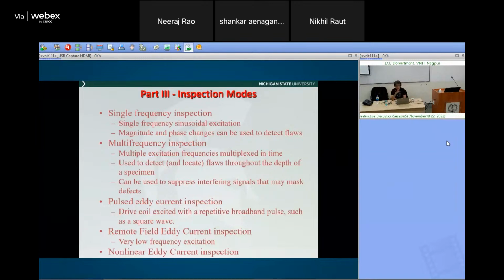At a very low frequency, the support contribution will be a lot more because support is on the outside. At very high frequency, the support contribution is less, because of the frequency and skin depth. So once they have these two different frequencies, they do a combination. They rotate and scale one of the frequencies, and then they subtract the two. The scaling parameters are all predetermined only to make this support signature look the same.